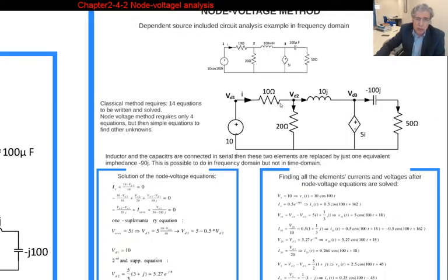The current of this resistor in terms of node voltages is (VD1 minus VD2) over 10, plus Is equals 0. Never write Vs here because this is a Kirchhoff current law equation. If you write Vs here, that means you made a fundamental mistake. Don't do it in exams. Don't do it anytime.